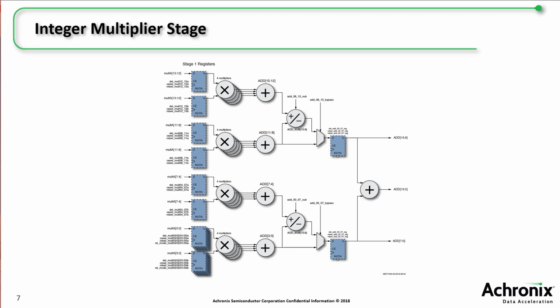The subdivision or combining of the multipliers is done automatically by the MLP, based on the input number format that the user specifies. The output of each multiplier is summed with its 4 nearest neighbours. In the special case of 16-bit values, the 4 multipliers in a group are automatically combined to create one 16-bit multiplier.